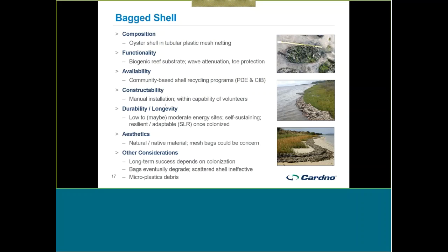It's largely done with manual installation. You may be floating several bags offshore in a dinghy or something like that, but they're hand placed. You don't need machinery to do this unless you're putting out large quantities of uncontained shell, but that's not really what we're talking about here for living shoreline settings.